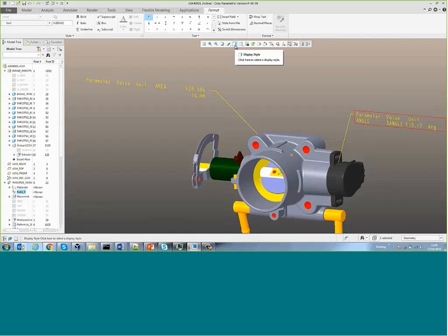So their fatigue analysis that was run when the product was initially designed was worthless because assumptions were made which didn't match reality. Now, if there had been a load cell under the bed which recorded the weight and recorded the duration, that data stream could have been fed back to a Creo session, and you could increment the input data for the fatigue analysis such that it reflected the real true life activity of what was happening with that bed.